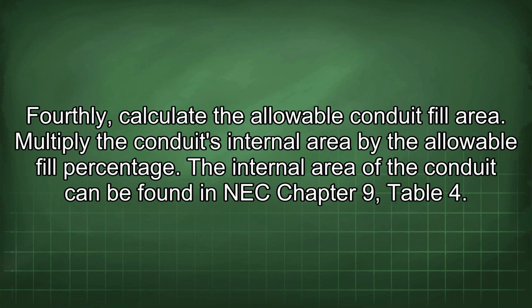Fourthly, calculate the allowable conduit fill area. Multiply the conduit's internal area by the allowable fill percentage. The internal area of the conduit can be found in NEC Chapter 9, Table 4.